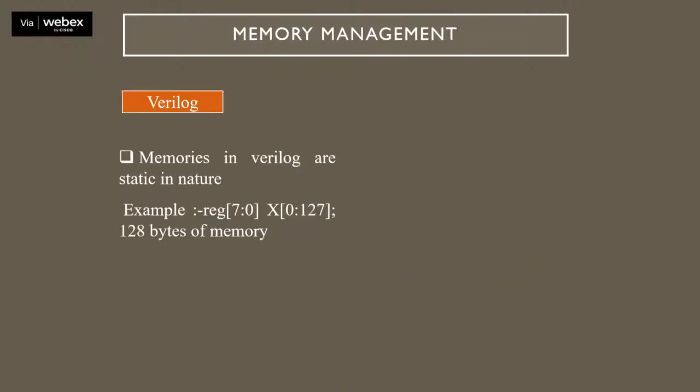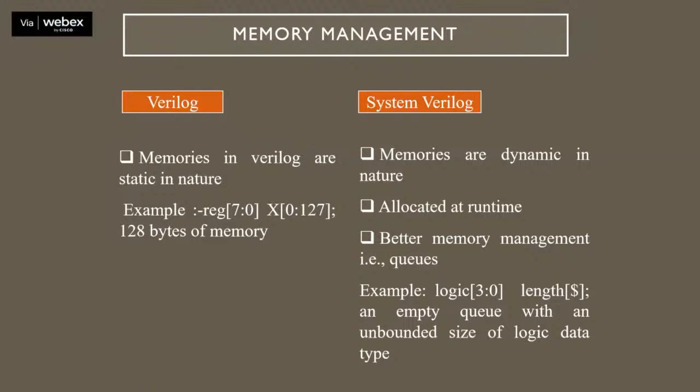Coming to memory management, when you design with Verilog, it is basically static in nature, so you usually use fixed arrays, and the ranges are well predefined. In System Verilog you also have the features of Verilog, that is, the fixed size array, or the size of the dimension defined at compile time itself.